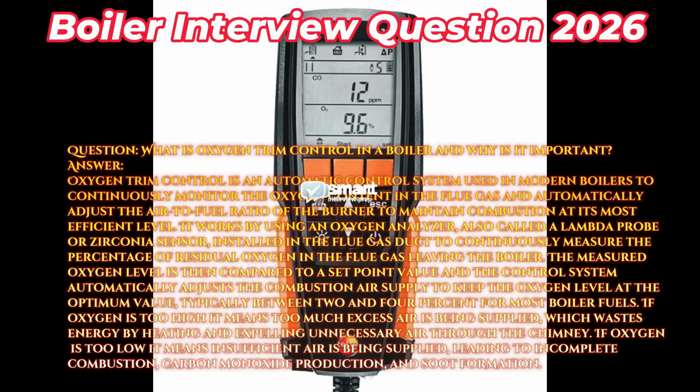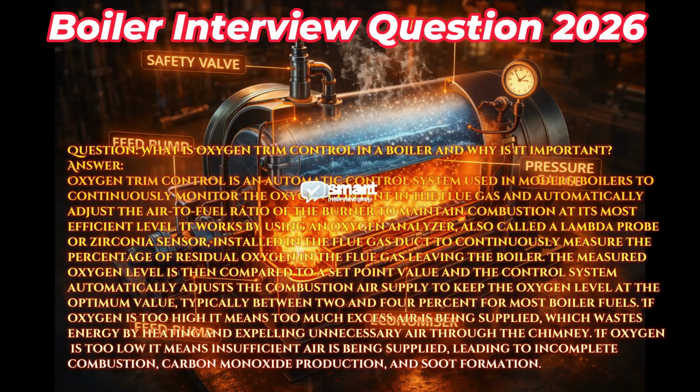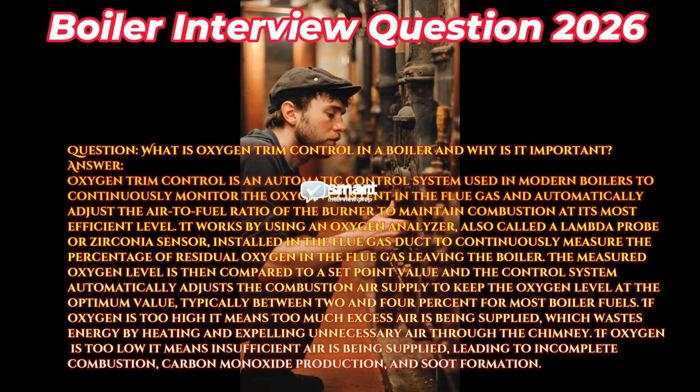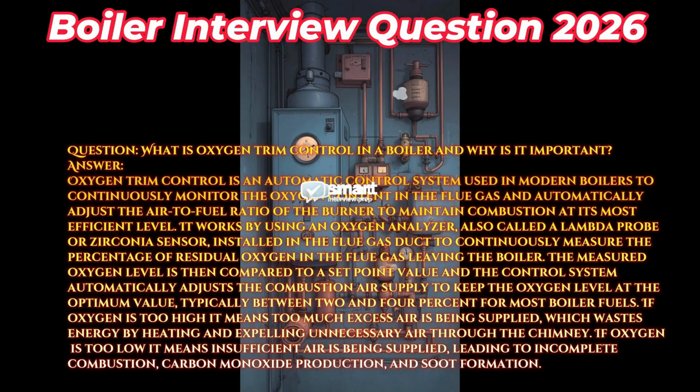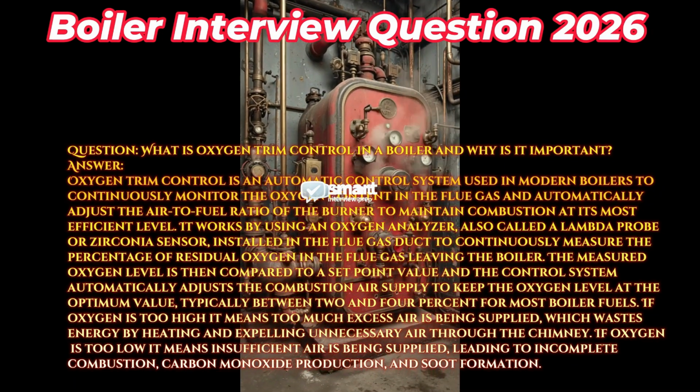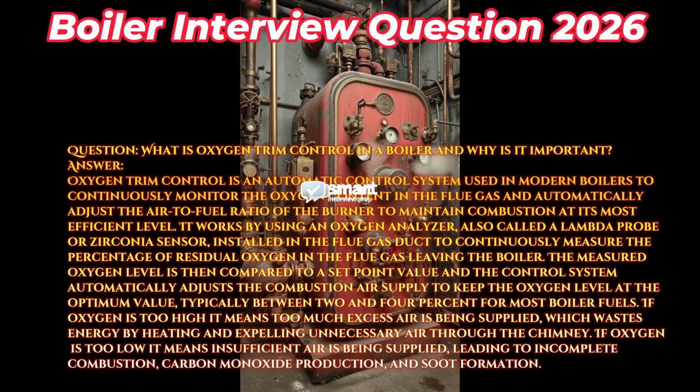It works by using an oxygen analyzer, also called a lambda probe or zirconia sensor, installed in the flue gas duct to continuously measure the percentage of residual oxygen in the flue gas leaving the boiler. The measured oxygen level is then compared to a set point value, and the control system automatically adjusts the combustion air supply to keep the oxygen level at the optimum value, typically between 2 and 4% for most boiler fuels.